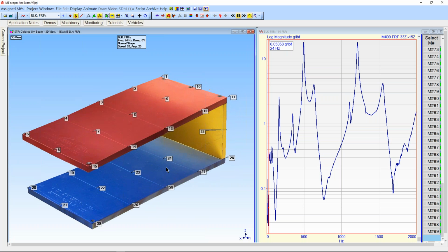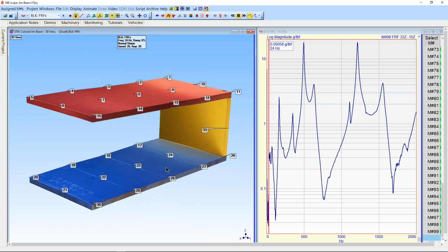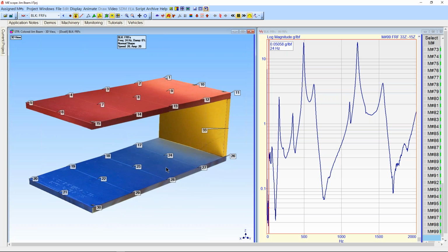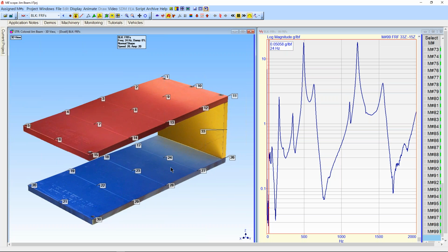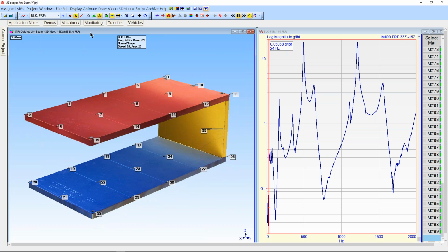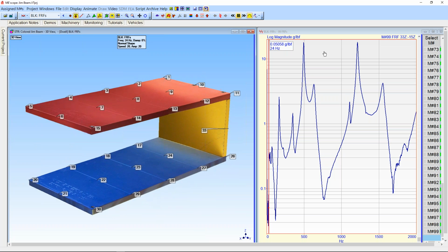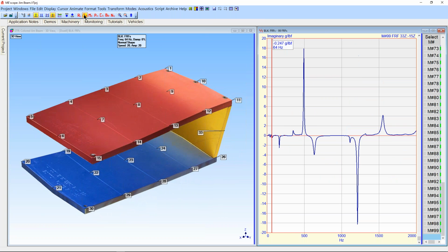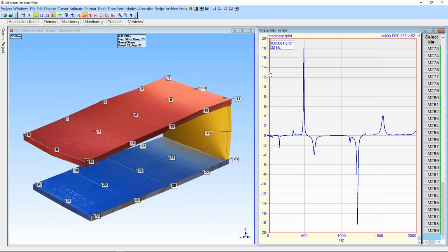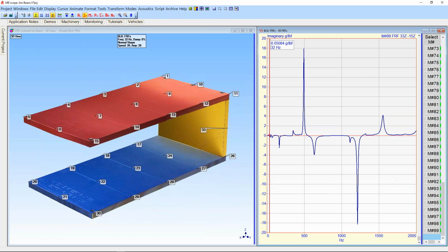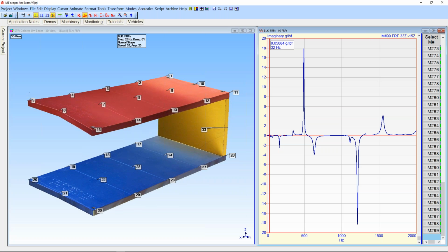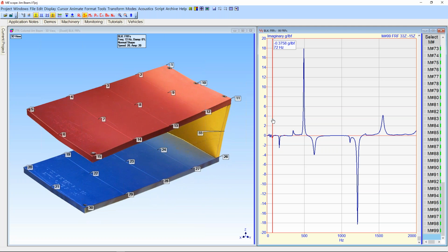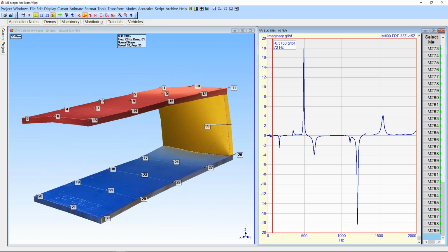So that's the first thing you want to do before doing any curve fitting, is make sure you have a good set of data. And that is what you will see down at the very low frequencies. Now, an even more accurate ODS would be to display just the imaginary part. So I'm going to click over here in my window, and now I have a command up here that says imaginary. So I'm going to just display the imaginary part of the data. And again, I see down here close to the lowest frequency a little peak in the data there at 72 hertz.